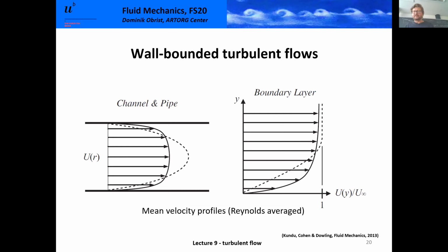This is the reason why most aerospace engineers, most engineers who design airfoils, want airfoils which have laminar flow on top of it. That's why they invest so much in keeping surfaces as smooth as possible to maintain them laminar as long as possible, because they want to reduce the gradient at the wall. They want to reduce the shear stress.